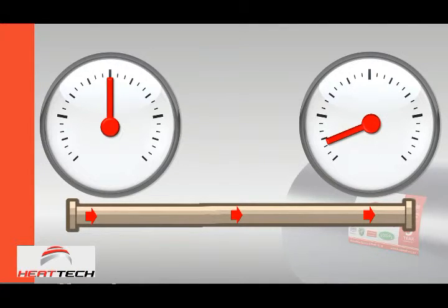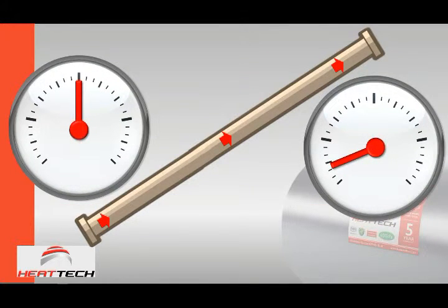What makes water flow from one side to another? What makes it flow in a specific direction? Water always flows from a high pressure to a low pressure. Now, we've discussed in the previous sessions the conservation of energy, that the total amount of energy between two points is the same, but you can transfer or change the type of energy. There are various things that can cause a pressure difference, but it is only the pressure difference that drives the water from the one point to the other point.